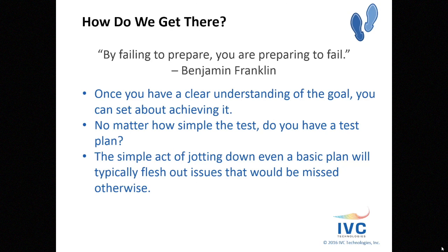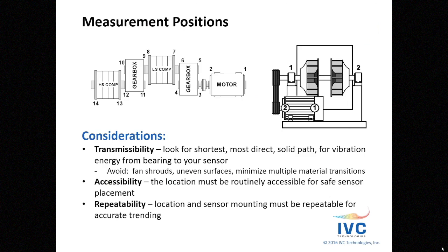It's that simple practice or exercise of going through in your mind, what steps do I need to carry out while I'm there at the test site in the field acquiring data. It allows you to identify things that, hey, I need to have provisions for power, or I need to have a test table, or I'm going to have to do these precautions from a safety standpoint. You always want to come up with a test plan up front before you ever get to the field.